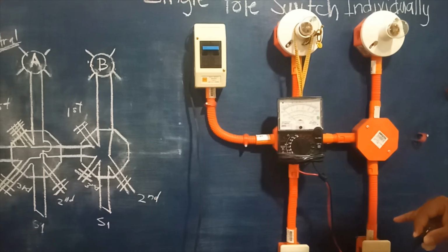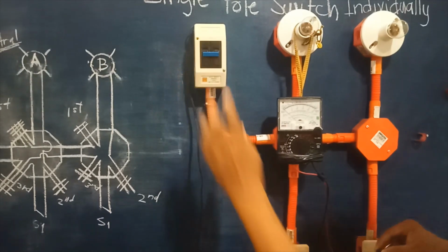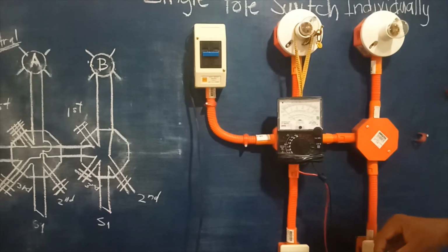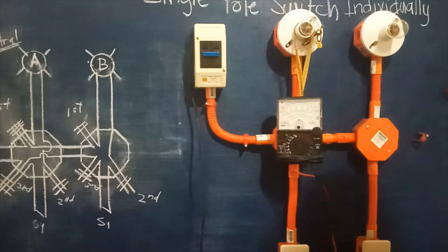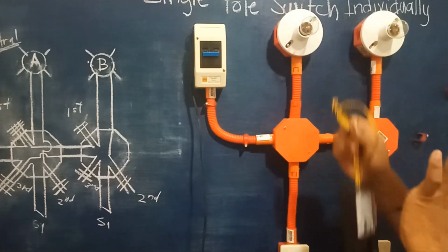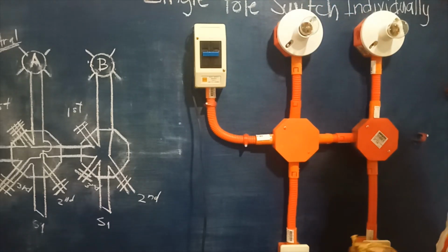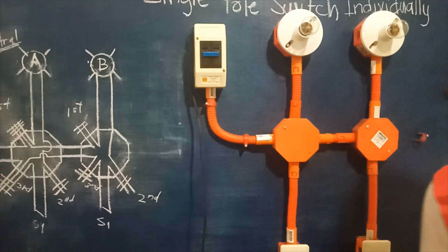So we will on first the other side, on, plus the other side on, then off from the breaker. Okay, to double check before we energize. Okay, so meaning to say there's no problem with our wiring connections. Then we have now the good signal to energize the circuit.